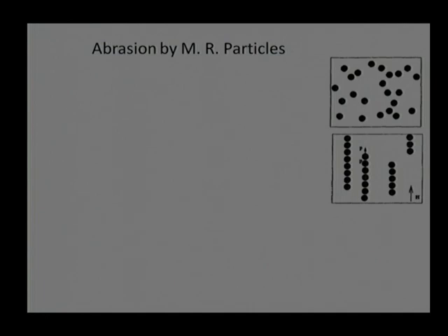They can make clusters. They can make 3-4 rows, 3-4 columns, not equal in size. A particle may get attached at this point, and the next particle will get attached at another point. However, between two columns there will be repulsion, so they will get separated, but filling of this gap is possible. That means it will not necessarily always be a chain. There is a possibility of cluster formation, which we have observed a number of times in the lab. It is cluster formation compared to chain formation, and this cluster formation increases the strength of the MR fluid, which gets solidified.